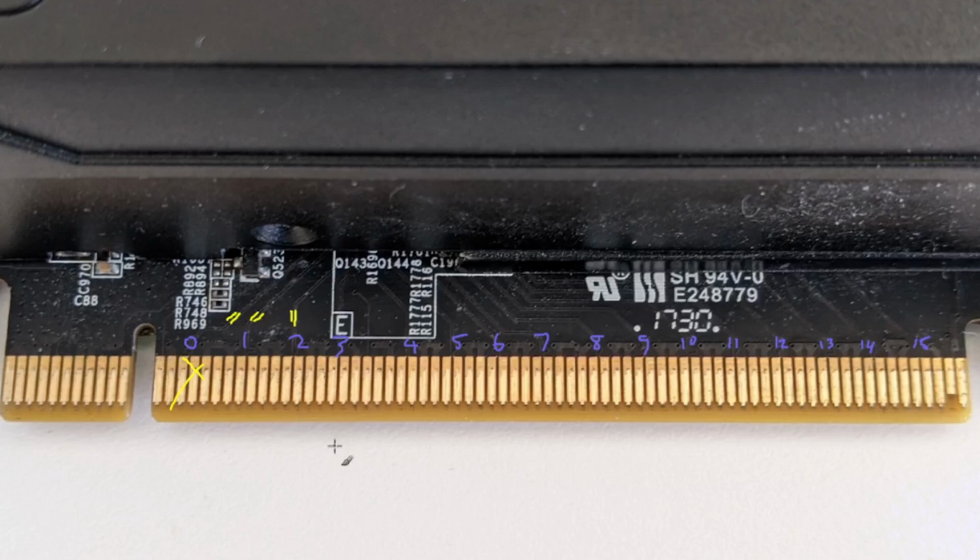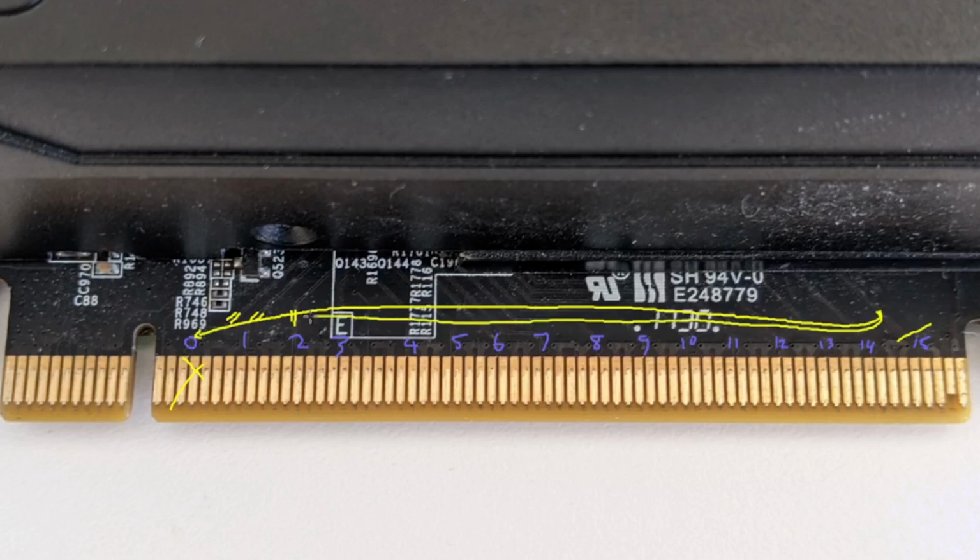The majority of modern graphics cards support something called reversed lane initialization. That means that lane 0 can be swapped with lane 15. And when technicians are repairing the cards, usually what they will do is cut the traces here and take the lane 15 differential pairs on the front and the back, and rewire them to the front like so for the 2 traces. And I'm trying to draw this as best as I can. And they will cut the traces here so that lane 0 does not go to the physical fingers on the PCIe card. What this is essentially doing is forcing physically the reverse initialization of an X1 mode on the GPU.